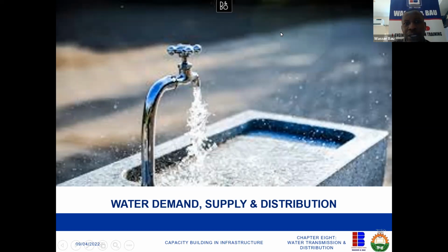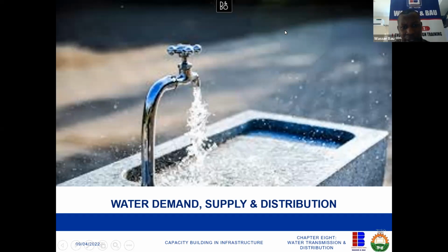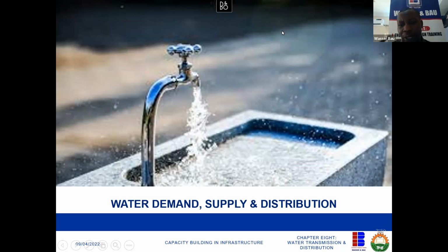The steps to design a water reticulation system for a district, for an estate, for a region, start with getting a map of the place and its topography. You need the map, the topography, the layouts, the history of the place, and the studies that have been done, so that you can use them to write your report. Next, you determine the water source: where is the water coming from and where is my elevated tank going to be?